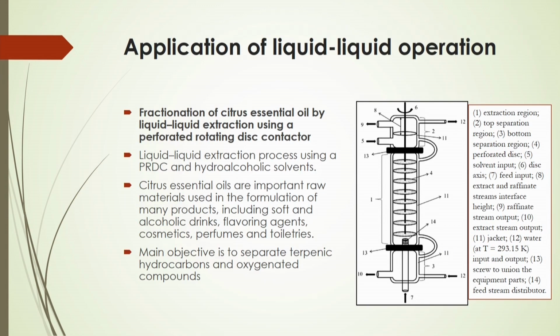And this is being done in a rotating disc contactor. In this contactor you will see some discs baffled in an axial location in the column, as shown here. Whenever it rotates, the liquid solvent and the oils are mixed with each other, making droplets, and through the droplets there is a transfer of unwanted components from one liquid phase to the other liquid. This is called extraction. Based on this process, the separation is done in liquid operation.